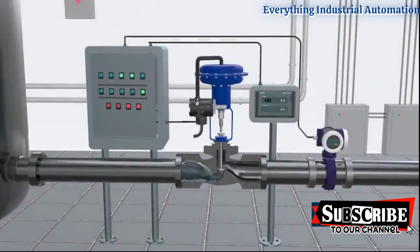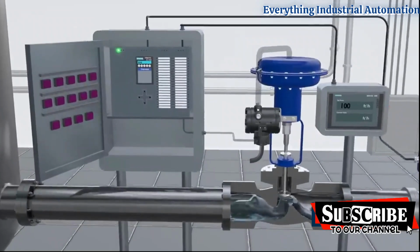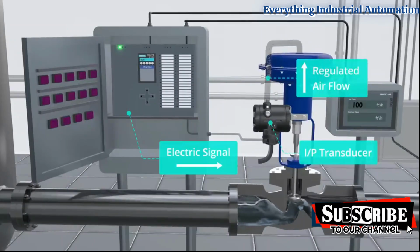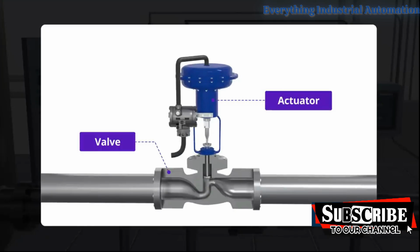A control valve receives a signal from a controller, such as a PLC, in order for it to move, resulting in a change in flow. Because the PLC signal is electrical, the control valve may require a device to convert that electrical signal so that it can operate. A control valve has two separate components: the valve and the actuator.